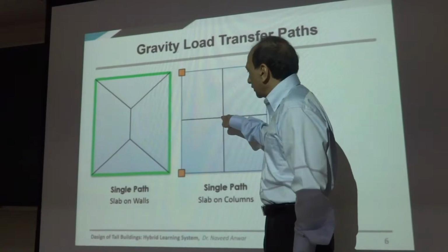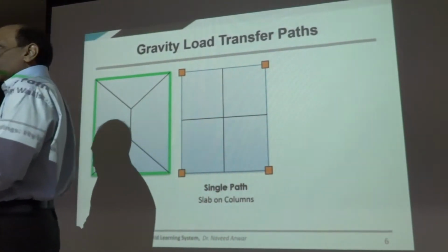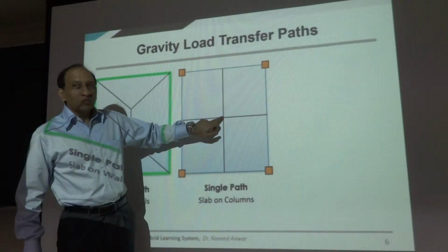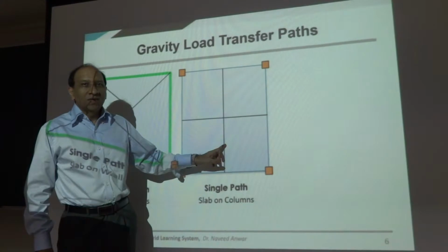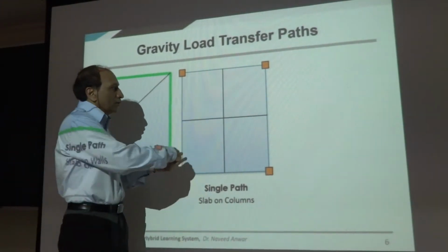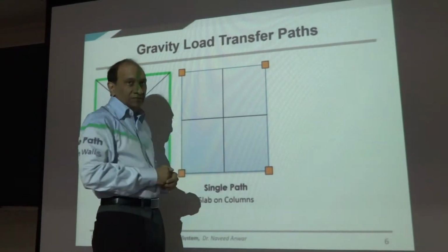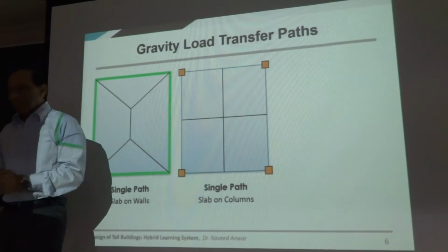I don't know what happens to the load which is right in the center. It's quite a confused load, right? Which column to go to. And right at this point, or right at this line. But traditionally, we calculate the load transfers to be like this. Actually, the load transfer will depend upon many things, right? But net load transfer, we can assume to be like that.